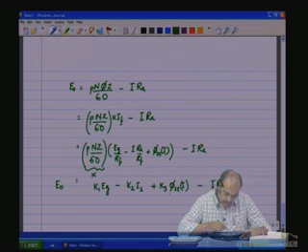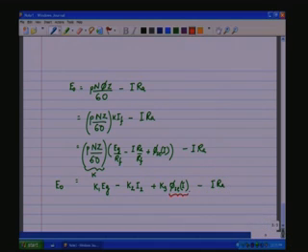Now, if we choose this such that it can take care of both the load component of the flux, shunt field flux, and the load component of the drop, then we have K 1 E g minus I into K 2 plus R A plus K 3 series field, which is a function of load.